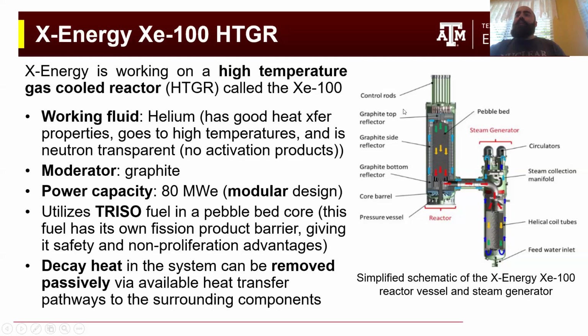It means that if you have a molten salt reactor, then the coolant has fuel within it. And that means that as that liquid fuel moves through your reactor, everything that the molten salt touches gets activated by the fission products and by things decaying. And so you don't get any of that with using helium as a working fluid.